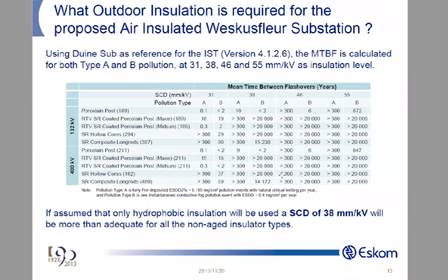Now, mostly on silicon, you don't get tracking, because tracking is a conductive path. So if you want to determine whether it's tracking or erosion, you would take a megger, 2 pins, and then you put it over the area with a few centimeters in between, and then you measure.